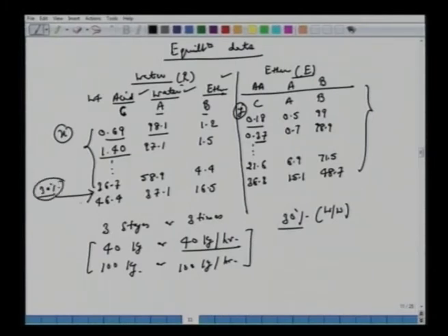Okay, and we have been asked to find out what are the raffinate concentrations, or find out the composition of all streams. Okay, so we plot, as we said, A, B, so this is the weight fraction of ether, and all we have to do is to only go till 0.3. So we have this equilibrium diagram like this.